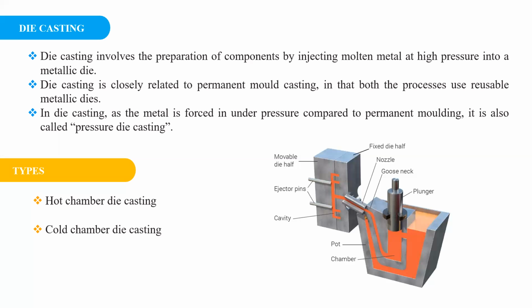In the sand casting process, there is a limitation because we cannot cast thin sections, as a defect called misrun will happen. Because of the lack of fluidity and high heat transfer rate of the mold, the molten metal will not reach the thin sections. Before reaching its end point, the molten metal will solidify, so there will be an unfilled cavity. That is called misrun.